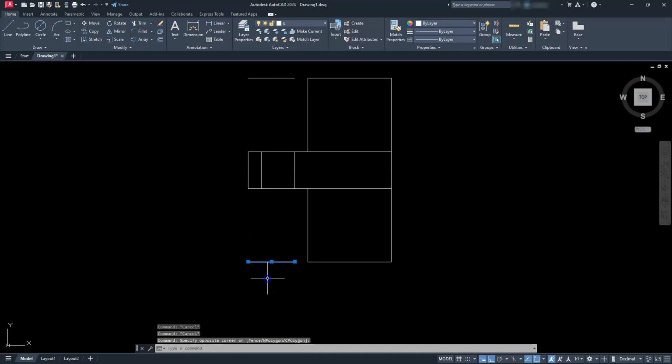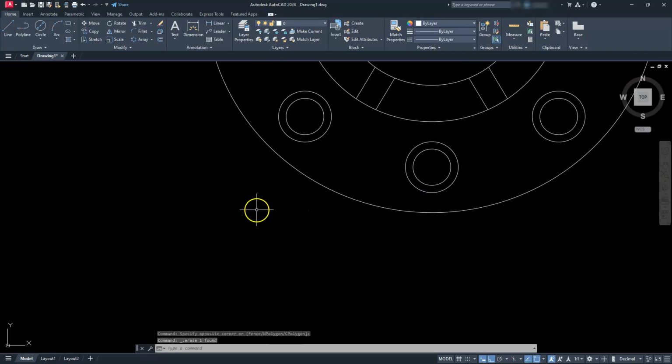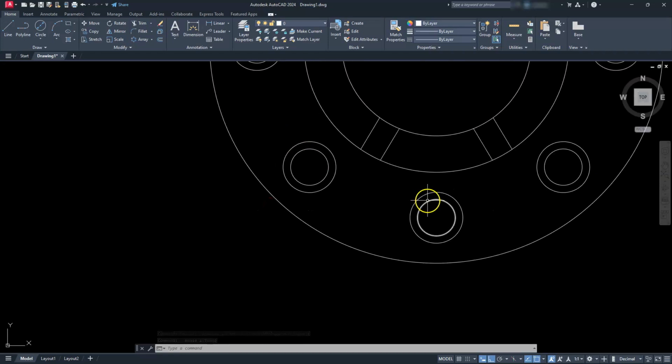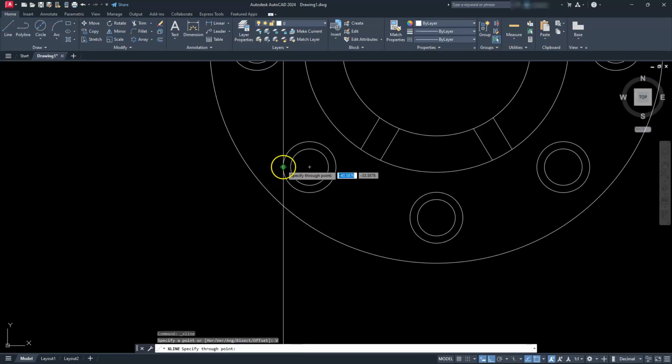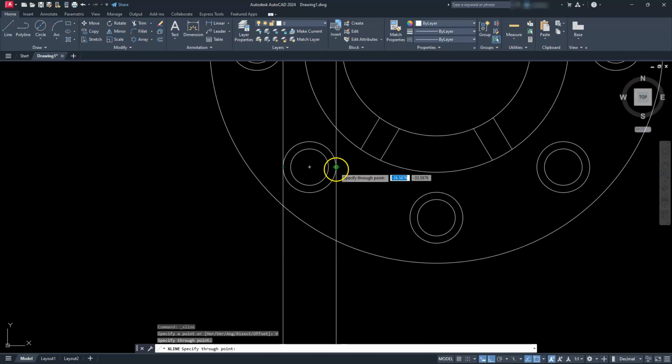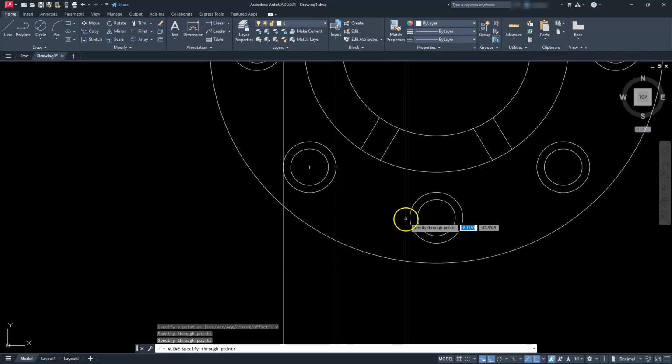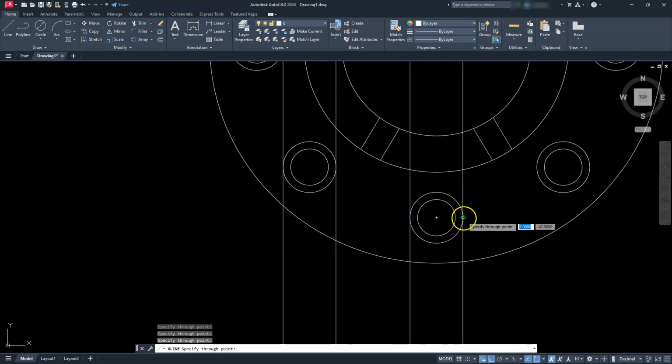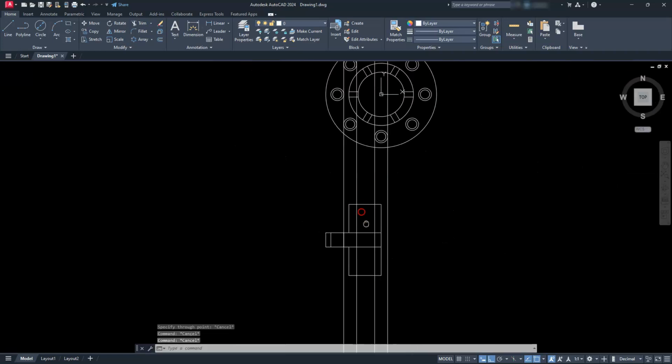All right, let's go ahead and erase these. Now remember that these are my outside circles here. So now I'm going to come and take a look at drawing these two. So I'll go back to construction line, vertical. Then I'm just going to hit these quadrants here. And now when I'm looking at it, I don't need to actually put in the center ones yet or the thickness of those yet. I'll let my section do that.